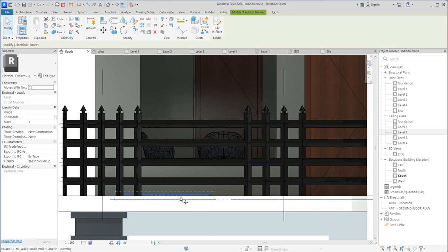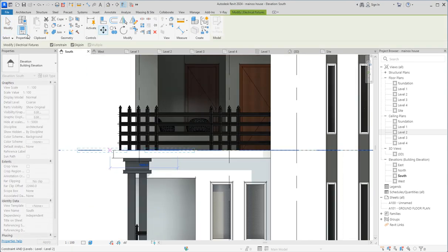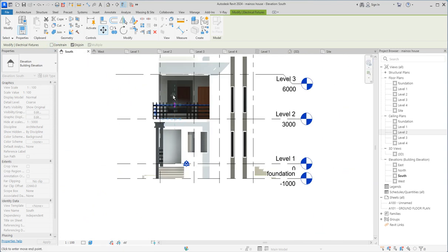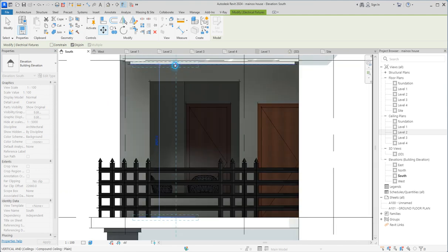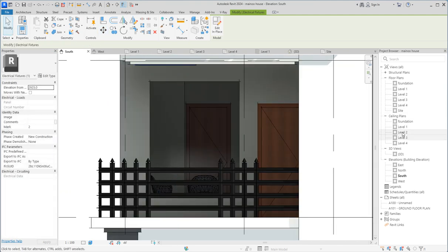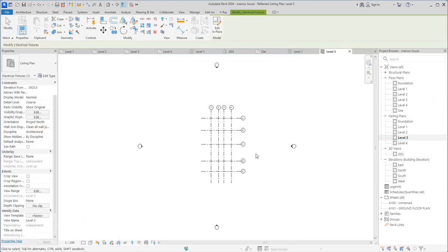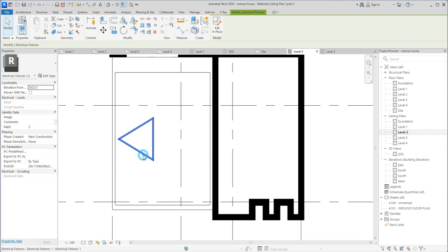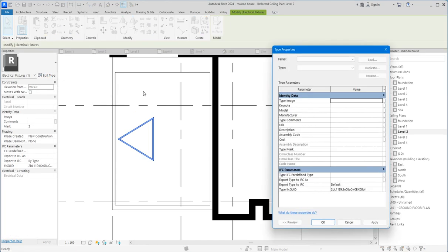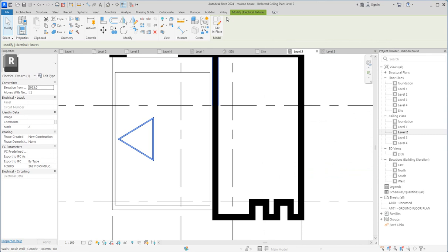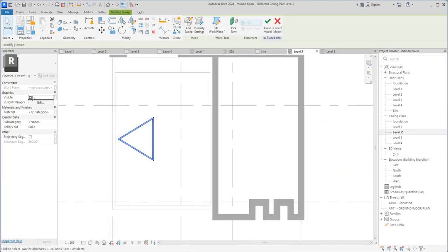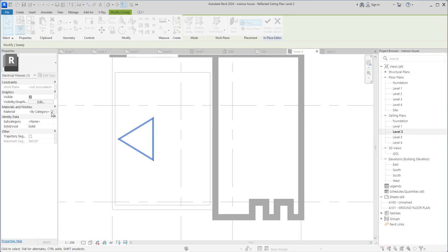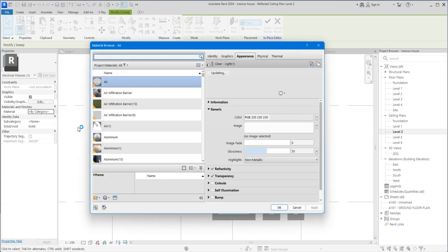So I did not do it in editing because I want that references to go along with it. So I'm going to click here, say constraint, and let it move and come to join this together. So at the level 2, level 3 is supposed to be seen. Level 2, sorry, that's the thing we have created here, which is okay. Now you can select the material, change every property of it, edit mode, select it and say edit category and name, edit material. So from there the material pops up for you.